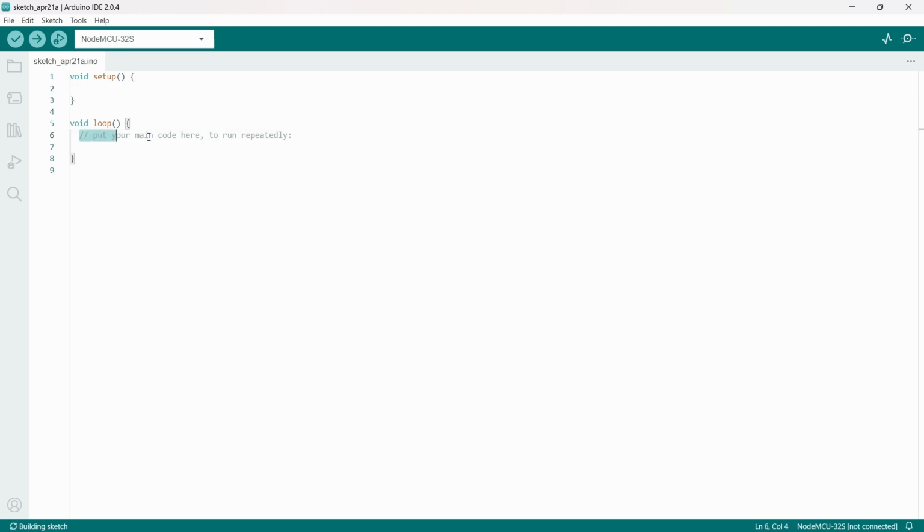So first we will create this code for receiving LoRa. What we have to do first is add the SPI package. Why are we adding the SPI package? Because the LoRa module communicates over SPI communication, not UART. There are lots of variations of LoRa; some LoRa series will also communicate over UART. The one I am using communicates over SPI. When it comes to the ESP32 and Arduino, there are lots of inbuilt libraries, so it is much easier for developing.